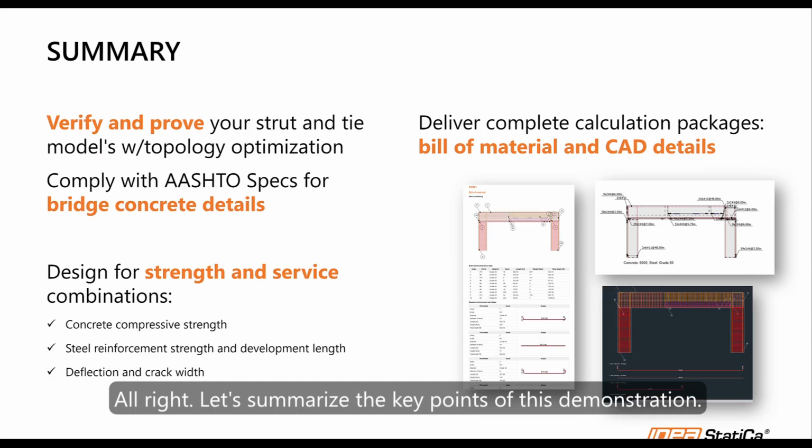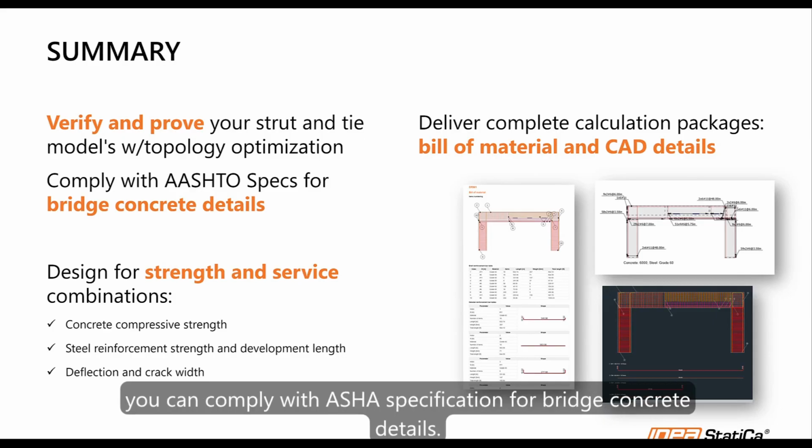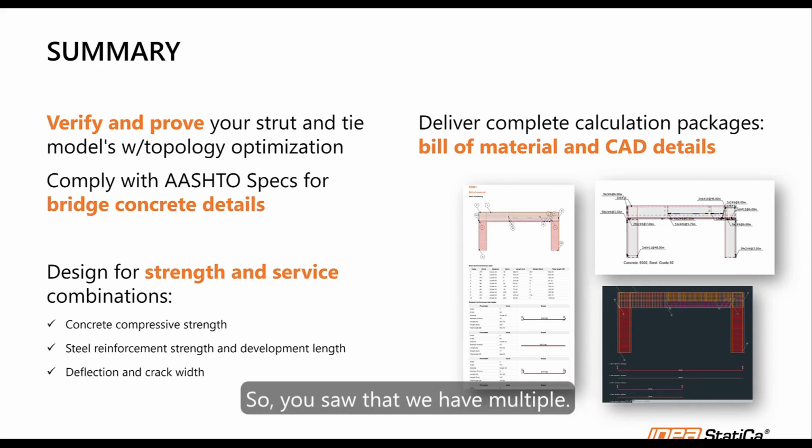All right, let's summarize the key points of this demonstration. So you saw that with topology optimization, you can verify and prove your strut and tie models. Also, you can comply with AASHTO specification for bridge concrete details. So you saw that we have multiple sample projects available in the application, and also you can start from scratch, right? Like I did with this beam frame.